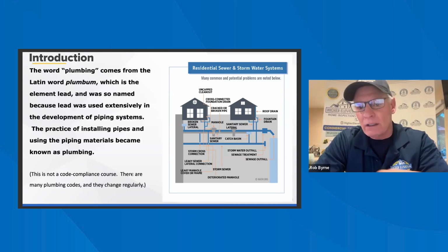If we have a newer house or a house using a cold water ground, we will typically see a ground wire here. That's part of the electric, but this is where we start to look. If it's a plastic water line coming into the house, of course, we can't use it for a ground. You're not required to remove all these. We wouldn't have known which one was the main, but if they're right next to each other, I'll typically look at both of them.